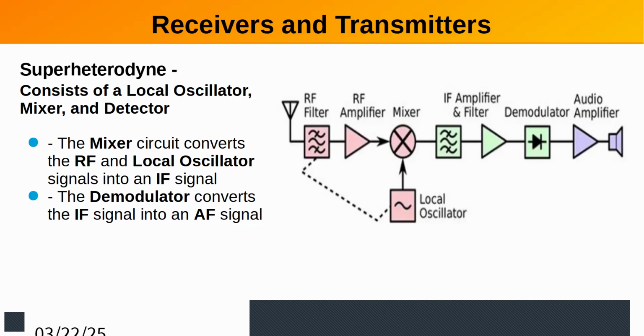Out of that, you get an intermediate frequency, which is that difference with the sidebands. And you filter that and demodulate it. In this case, they call it a superhet. To me, it's only a heterodyne because it only has a single conversion. But I'm not going to argue with them. Then you demodulate it with your envelope detector and amplify it and listen to the music.